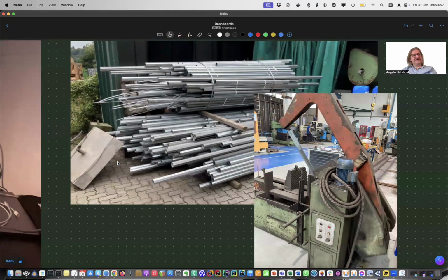A simple example of that, one time we did a project for a factory where people were actually checking small pieces of metal that came out of a cutting machine. Some were okay, some were defective, and there would be an operator there moving the correct ones to the left and the defective ones to the right, or the other way around. In cases like that, you can put in a simple detection mechanism with an inductive or capacitive sensor, for example, that simply counts how many products come by during the course of a minute, a day, an hour, whatever level you want to measure. These are simple things that we can add, even if things are not monitored in a digital system.